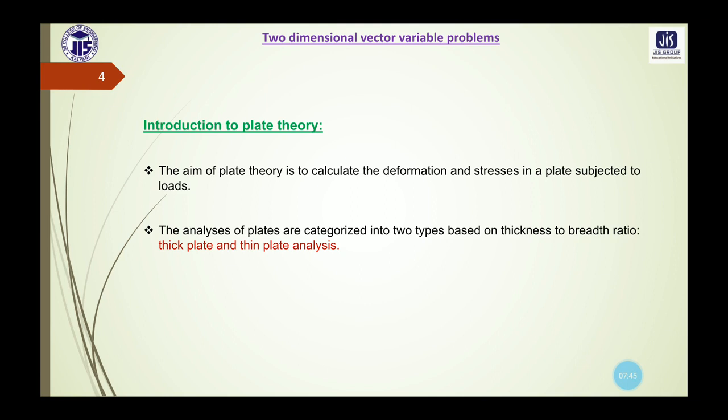And the well-known Kirchhoff's plate theory is used for the analysis of the thin plate. But in case of the thick plate, we use the Mindlin plate theory, in which the effect of shear deformation is included. So these are the different theories applicable to thin and thick plates. For thin plates we use the Kirchhoff's plate theory, and for thick plates we use the Mindlin plate theory, where the shear deformation is included.